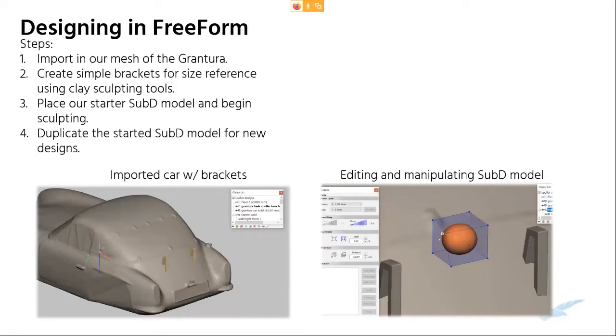And so designing in freeform actually is really easy. The real big steps are I took this car model, I imported it into freeform, I designed 2 brackets real quick just so that way I have a reference of how everything is size-wise. And at that point, I'm able to place my starter sub-D model into the proper position and begin sculpting or pushing and pulling with that sub-D model.